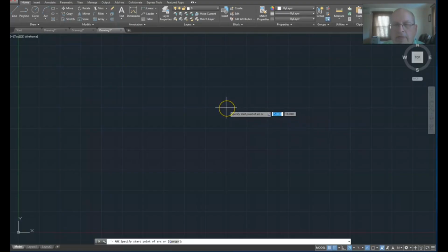I'm going to choose as my first point the intersection of the heavy lines here, where the big blocks intersect. That will be my first point. Then I move to the right one large block and down one large block, and that becomes my second point. Then I go down one large block and to the left one large block, and that becomes my third point. When I'm all done, I have drawn an arc that constitutes exactly half a circle. And that's important. You should have exactly half a circle, no more, no less. So it should be 2 large blocks high and 1 large block wide.